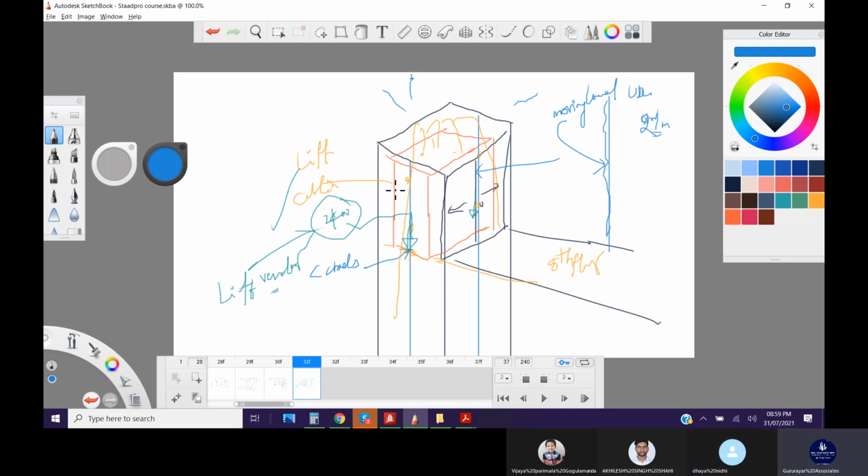If you have a brick wall, the vibration will make the bricks crack, and slowly, one by one, the bricks will fall. The brick wall will get damaged. So for that purpose we always have a concrete wall in the lift. Not only the lift, but wherever there are equipment handling units, it should be RCC only, not bricks or timber or other materials. Always reinforced concrete only. So that's why the shear wall is required.